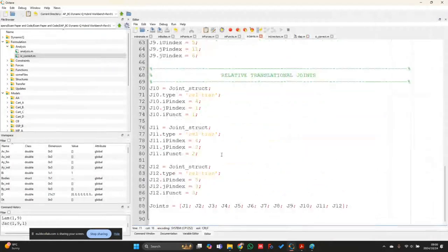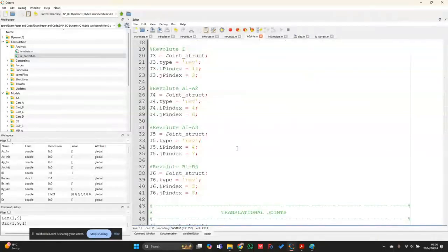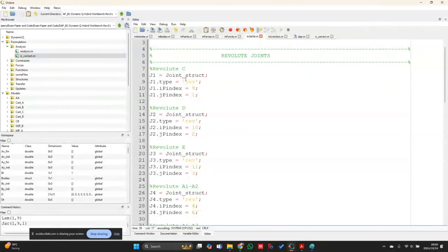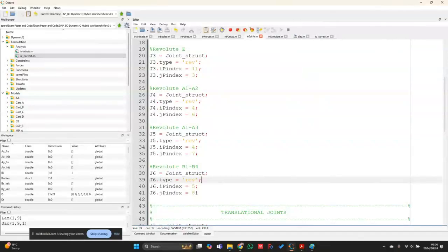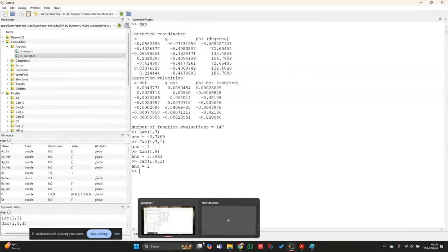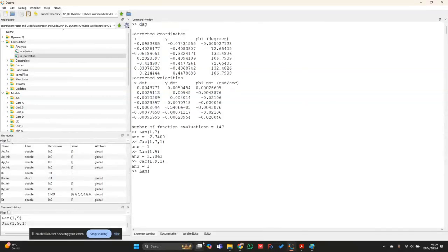So to go and find this, I just head back to my in joint, and the one that I'm interested in now is the revolute joint over here. So if I check, that is 2, 4, 6, 8, 10, in this case 11 and 12 are the x and y components that I want to consider. So to go and find this, I can over here just say Lagrange multiplier 1 and then 11. Okay, so that would be the RBX value.